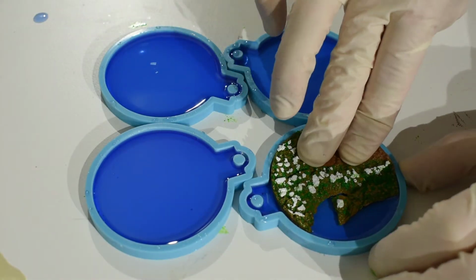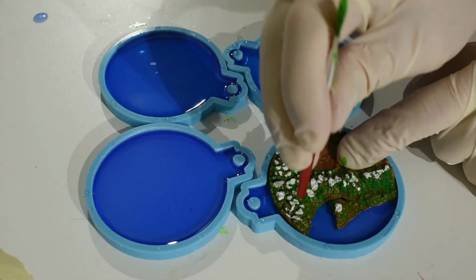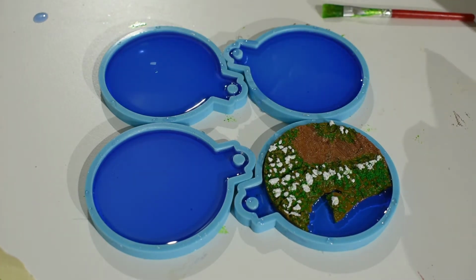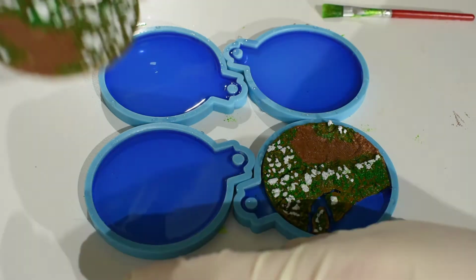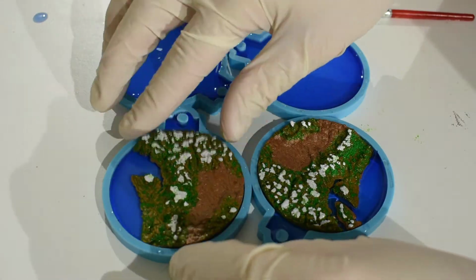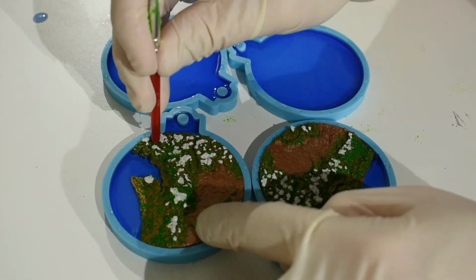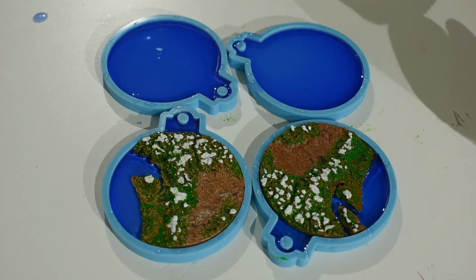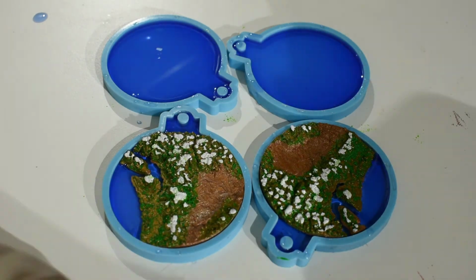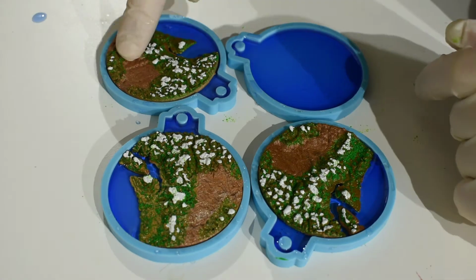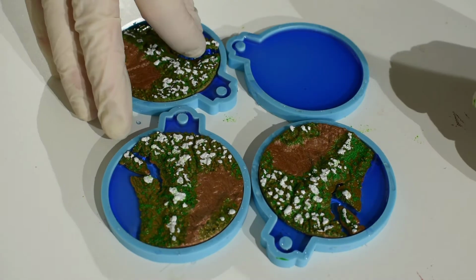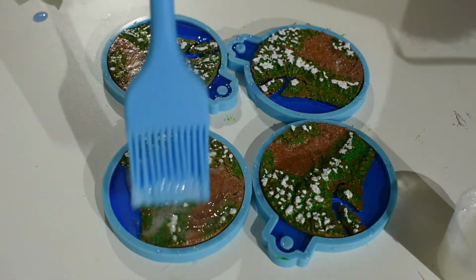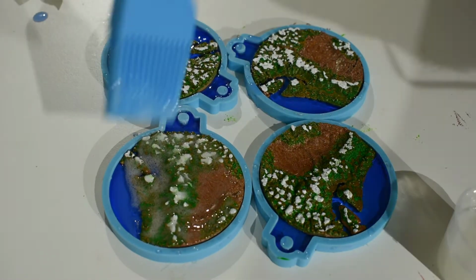I found in my first few tests that if you put the 3D prints on the resin shortly after they've been poured, it will sink somewhat into the surface. So while it's fun to show the future impacts of climate change, I wanted my land above the water. The solution for this is simply waiting 3 to 4 hours after mixing the resin to place the 3D prints. At this point, the resin is thick enough that the prints won't sink, but can still be stuck in the resin.